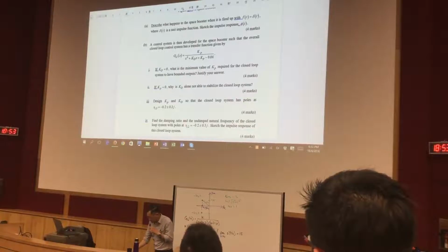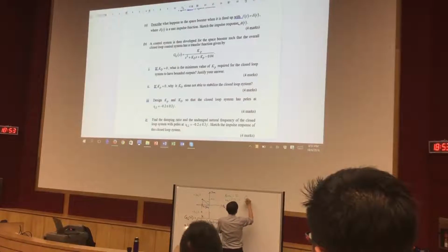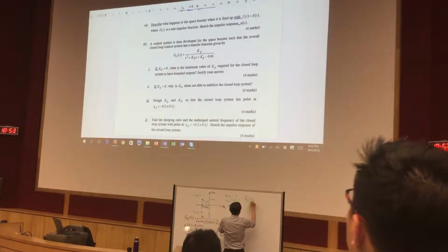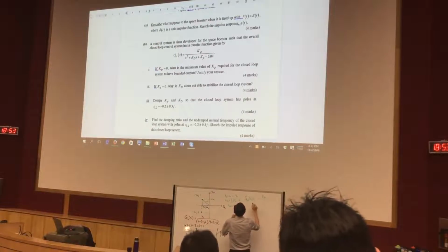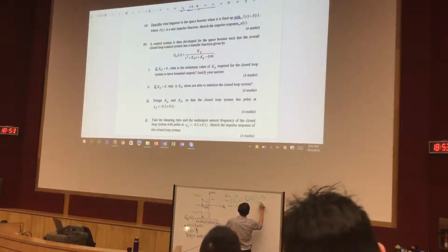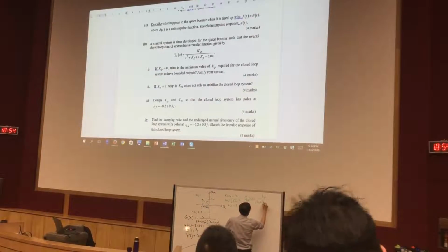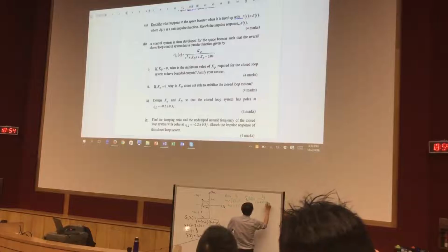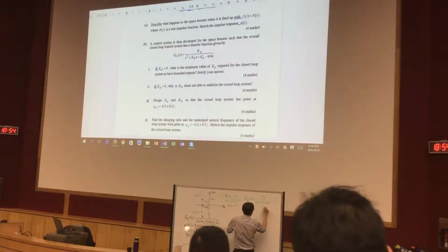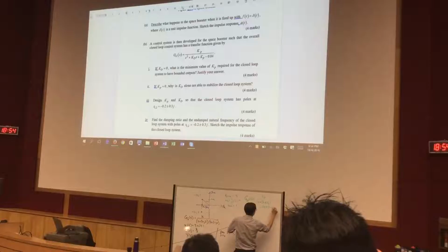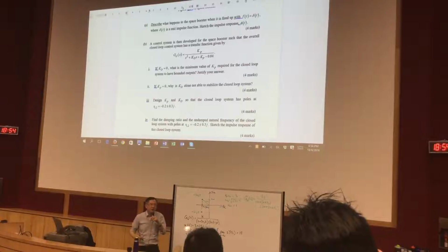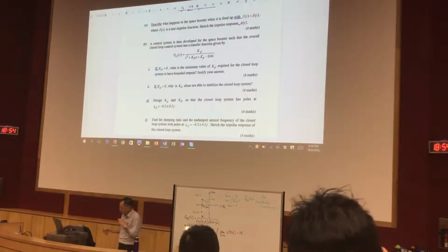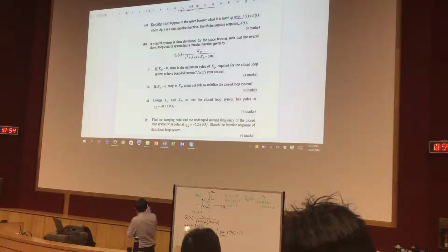Alright? So since you are given the poles, then what you have is that your closed loop denominator is (s plus 0.2 plus 0.3j)(s plus 0.2 minus 0.3j). Work it out. Okay, clean it up and compare coefficients. That's it. That is part 3.